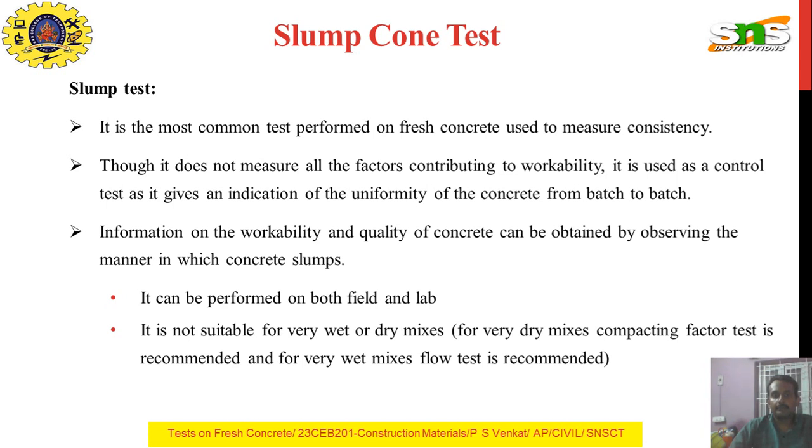It can be performed both in field as well as laboratory. For wet mix, slump cone test is most preferably used, and for dry mix, compaction factor test is most recommended.